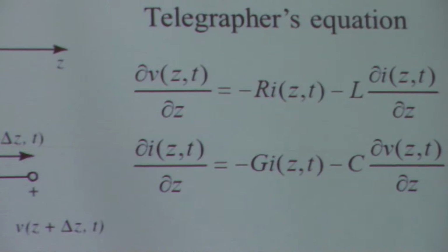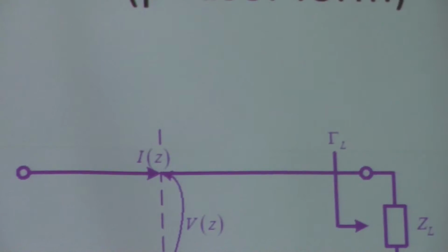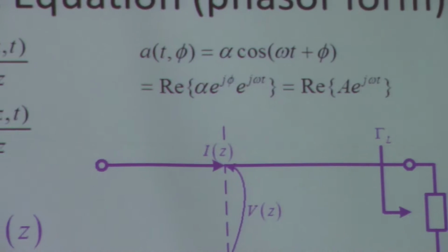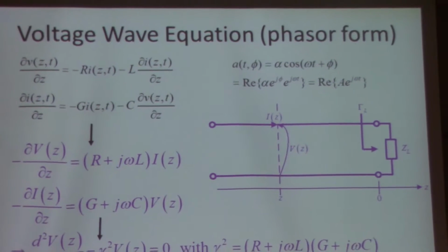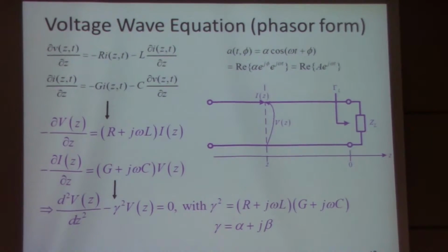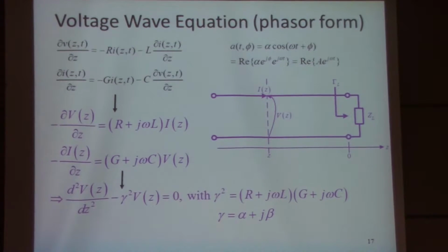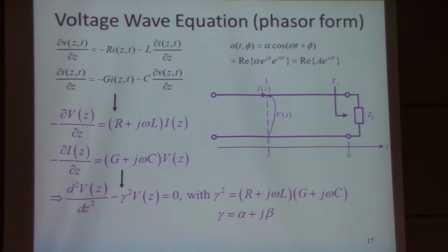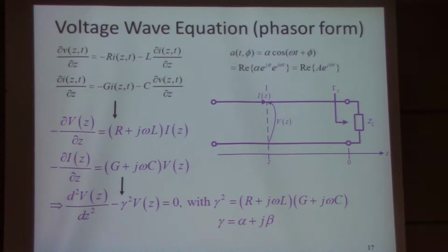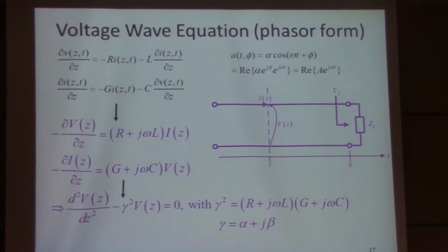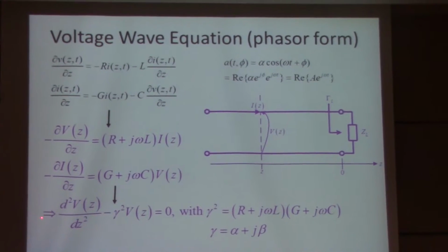Okay, so when the transmission line is given, these parameters are given. Then you see the voltage and the current. Now they propagate. They actually are waves. They are not like the DC stuff. In DC, you apply a voltage here, and we assume all the points on your line share the same voltage, right? So you don't have time for the propagation of your voltage. But here you do need that. So it's a wave function.